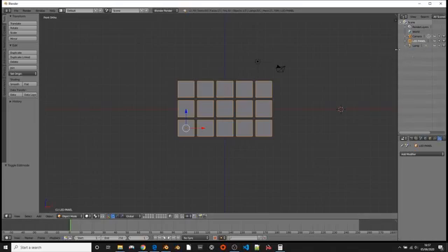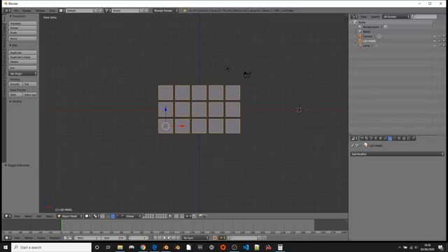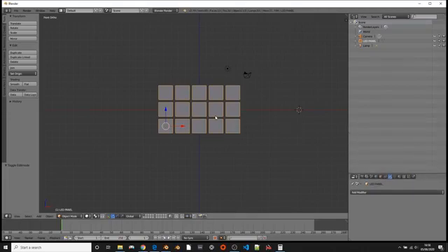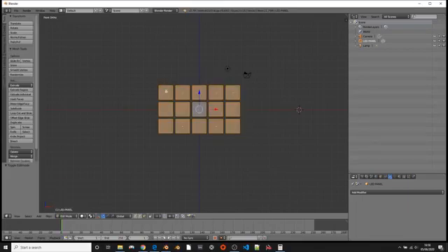So let's just bring that over a little bit. So we're going to see some things getting added into here. I'm just going to make the window a little bit bigger so that we can see anything. There we go. So if I go back into object mode, we're on face mode, which is great, and they're all selected. If you press P, that gives us the separate option. And if we separate by loose parts, what it's going to do, rather than us having a single object, we're going to end up with 15 different objects all within the model file.